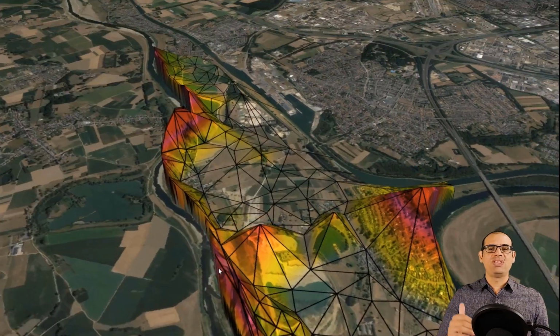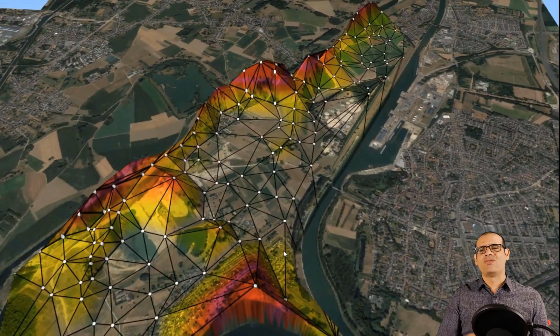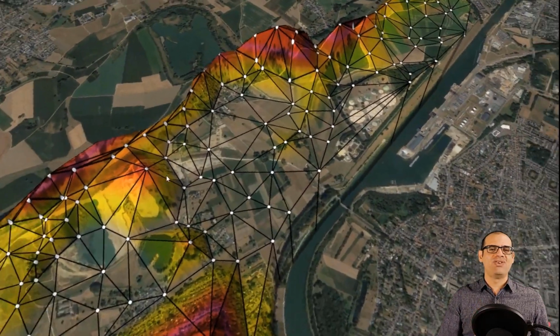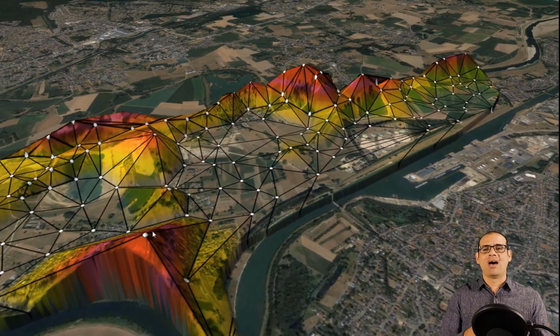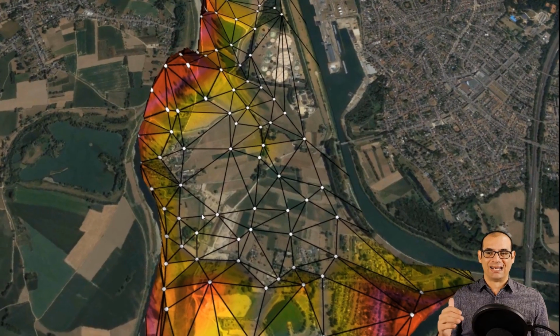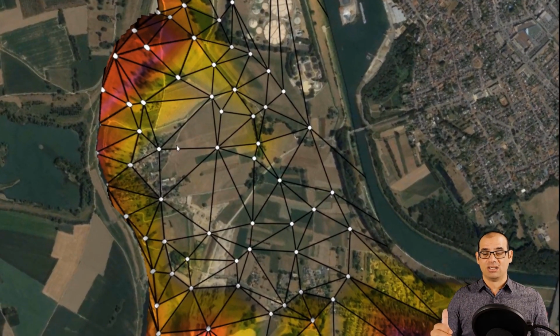This technique of interpolation is undervalued because currently there are a lot of software packages that can create very sophisticated interpolated maps with just a few clicks, like Kriging interpolation. However, in order to execute a proper Kriging interpolation, you have to do an exploratory data analysis, and it requires geostatistics knowledge. However, to apply TIN interpolation, you don't need to have a strong knowledge of geostatistics, and